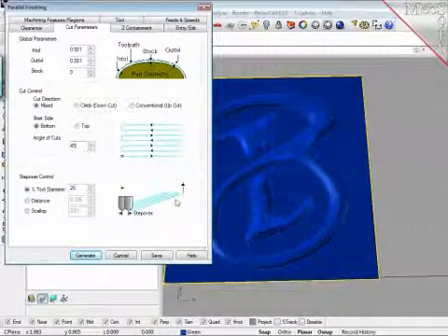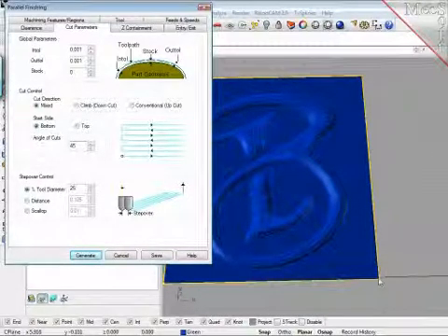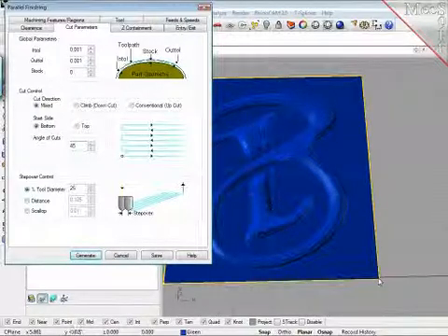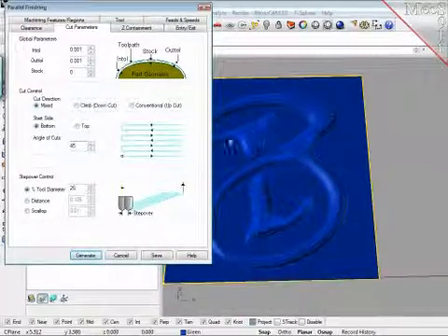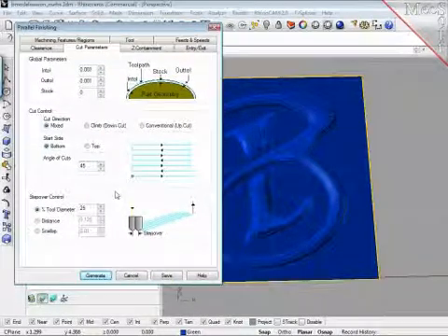What we will do with a 45-degree cut is we will sink in here basically like a drill, and the first move already which we will create will be a step to the front and a line to the back. However small it is, it already has a gap to the back, which will only grow further and further as we go in. So again, MecSoft to the rescue. It allows us to define those things.